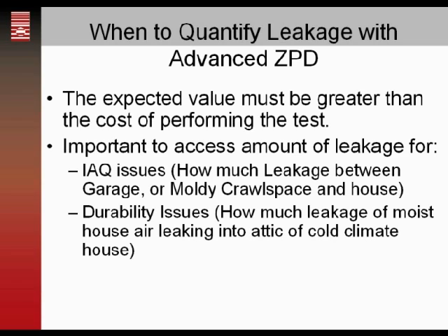So the expected value of doing zone pressure diagnostics must be greater than the cost of performing the test. And if you have a pretty straightforward rambler where all of the bypasses are accessible, it probably doesn't make a lot of sense to be doing the advanced zone pressure diagnostics testing.